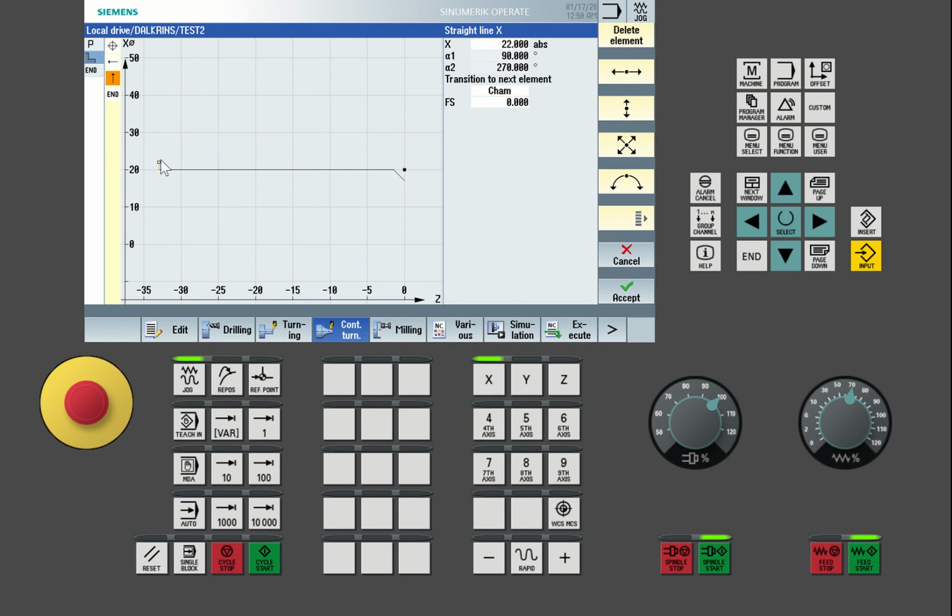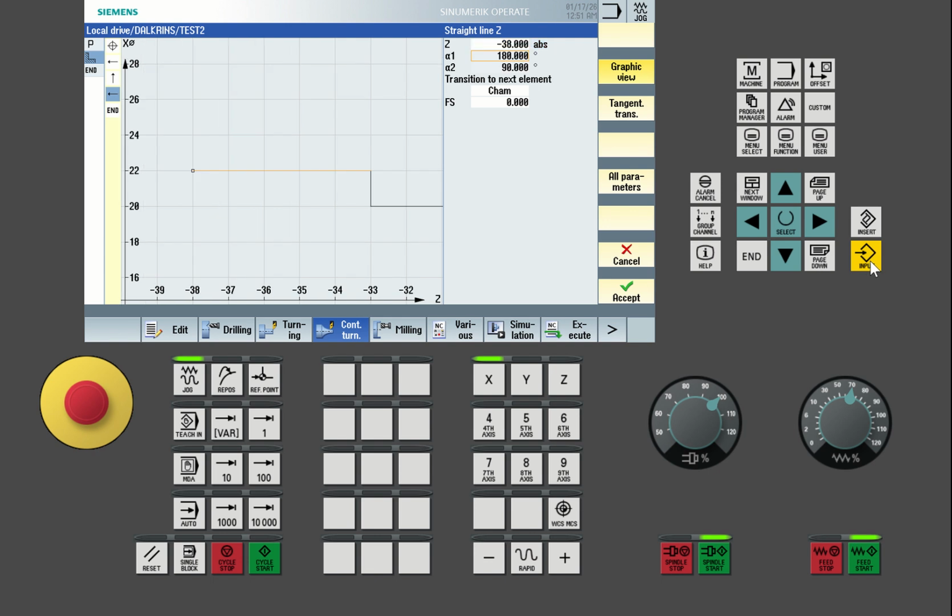And then from here we go to horizontal again. We want to put the Z value from this point, which is 33 plus, let's say, plus 5, so you get 38. Input. So this is the value we have, but remember it has a chamfer, so this one should not be this one.